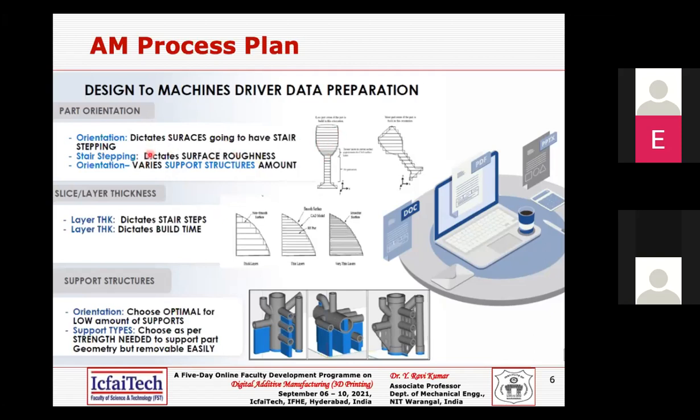In terms of stepping, that is while slicing, we may anticipate this sort of error. You cannot eliminate it 100%, because by nature these layers are getting stacked. That error may be more tedious wherever you have a free-form surface. If you have a flat surface, your staircase effect may not be that quantifiable.